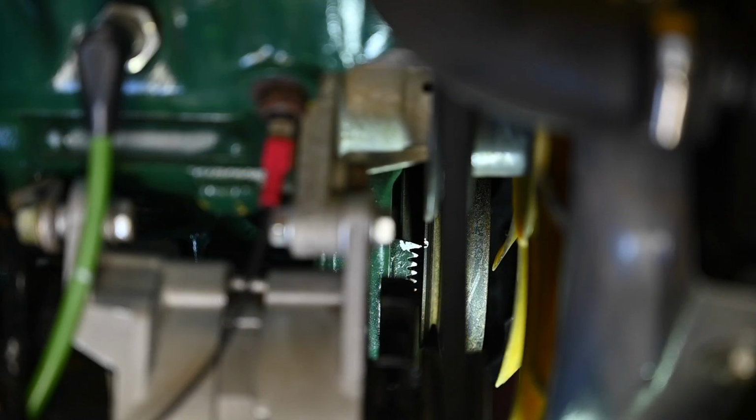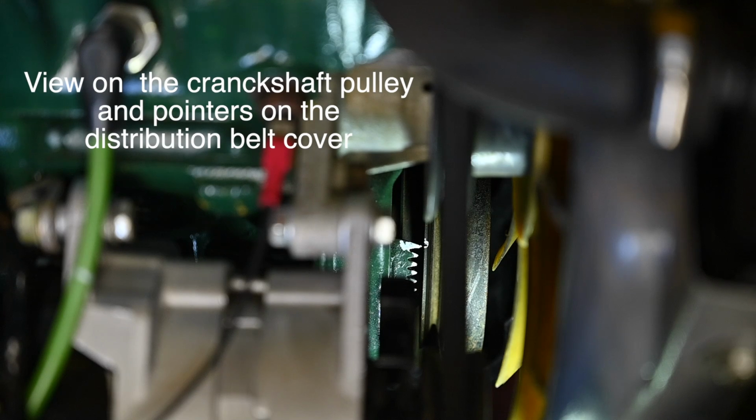And all the way in the bottom there, you can see the big white marker and the smaller ones. Well, the big one is my top dead center, and I positioned my engine so that the flywheel marking is exactly top dead center. So now I know that this pointer on the distribution cover is correct. I also have a dot on my crankshaft pulley, and it actually lines up. The small little dots that you see, that's each time 4 degrees advance. So the first one is 4, the second one is 8, and so on.